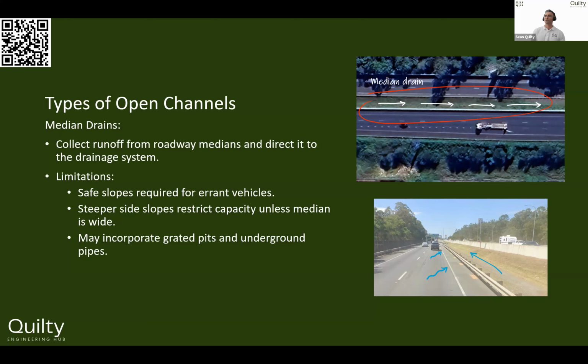Now, when you get to quite large roads, quite wide roads, whether they're arterials or highways, you end up having 3, 4, 5 lanes plus shoulders. You get quite a large catchment area where it's just the road picking up the stormwater. And so we've got to control that water runoff. And usually where you have these really wide roads, they're also of a really high importance. Because they're an arterial road or a highway, you can't afford these roads to become flooded in frequent events. So they can't be flooded every few years. You want to make sure they're dry as much as possible.